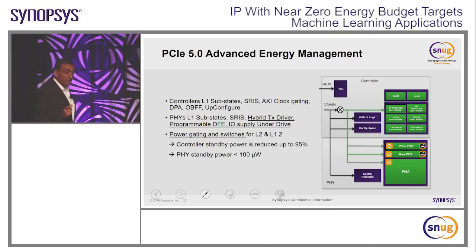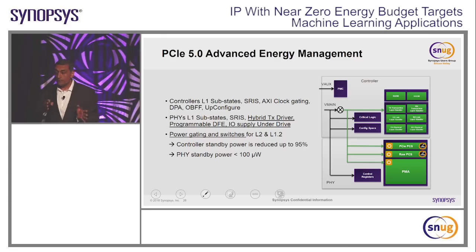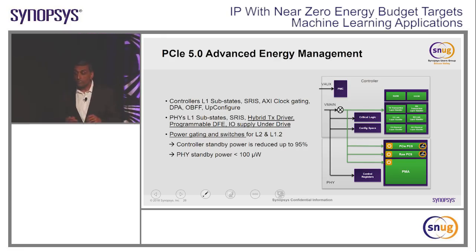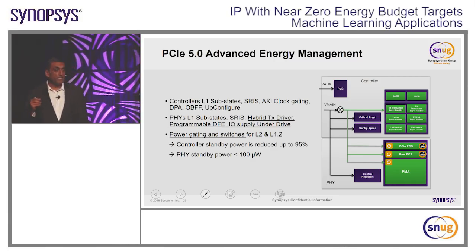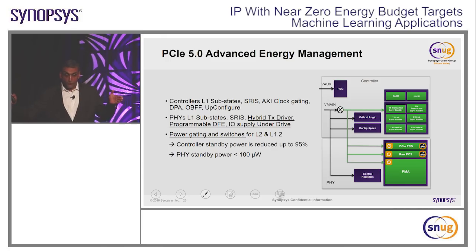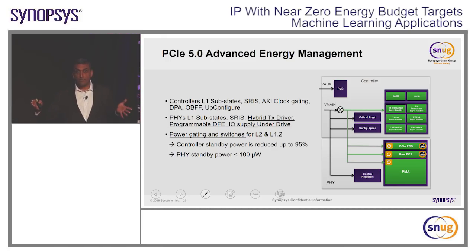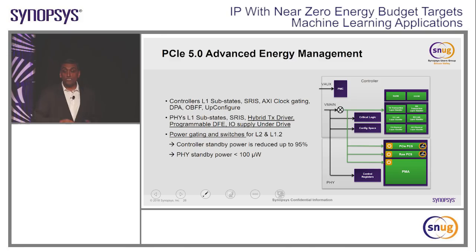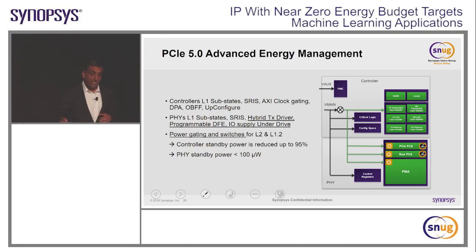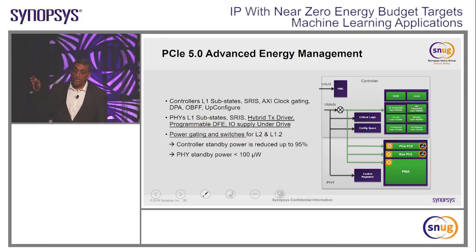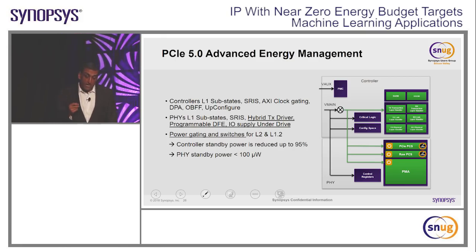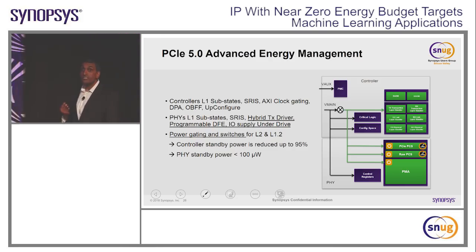looking at the noise profile, and essentially looking at the design from a common mode architecture, a current mode architecture and a voltage mode architecture. And you're making those trade-offs in terms of power supply rejection ratio and launch amplitude. PCI Express Gen 5 has a very interesting specification related to the channel, i.e. you're communicating between two links across PCI Express Gen 5. The medium in between is called a channel. It can be a board FR4 material that can generate noise at very high frequency. So the equalizer used on one end helps to recover the signal in the noise. And if you reduce the power of the DFE, if your channel is benign, you also save on power consumption.